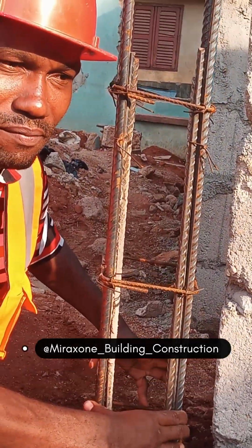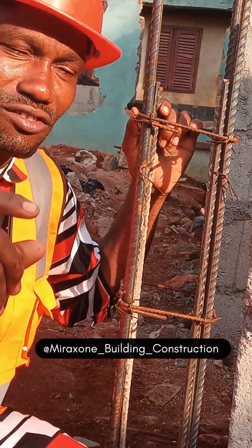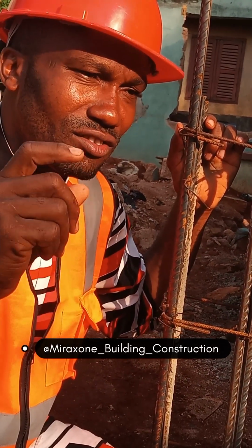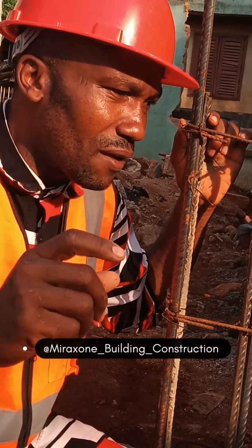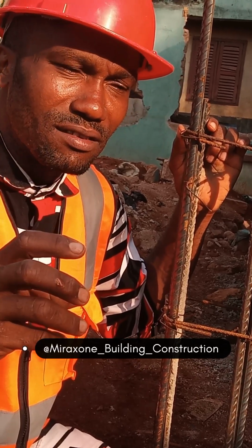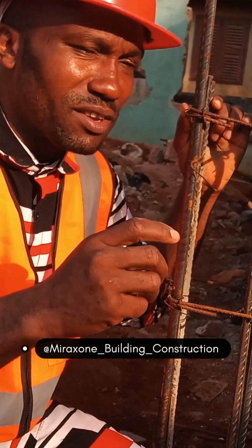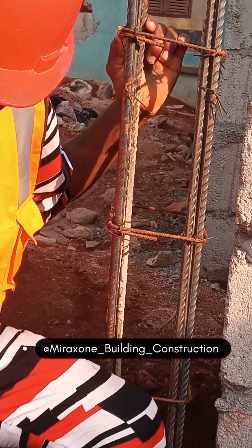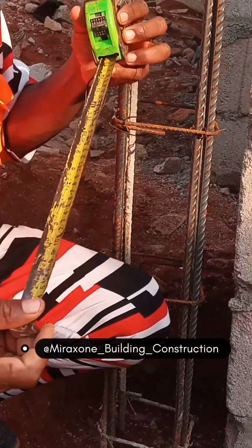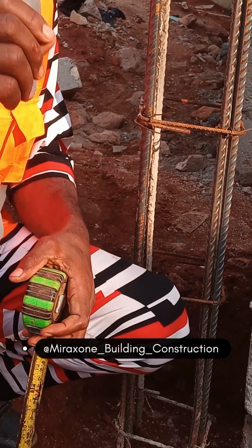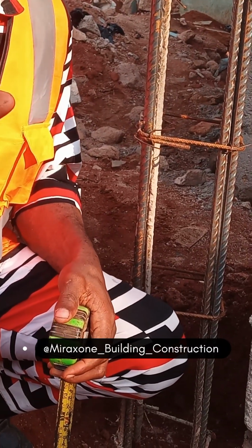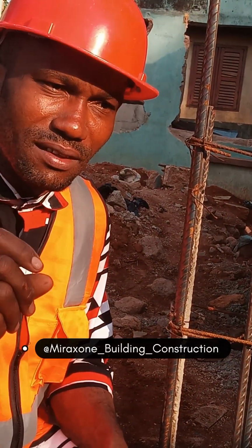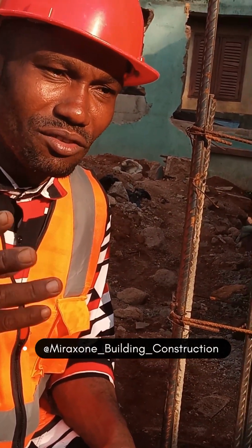Do you understand me? These things matter in structural arrangement. When you are carrying out your structural work, when you are implementing your structural components, please, you have to bear this in mind, especially for columns. This is how you have to place it. Okay, now let's go on. Look at my lapping length. I told you that the minimum lapping length I use is 720 millimeters. Okay, that's for me. I don't know about you.